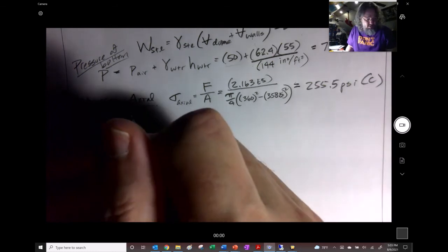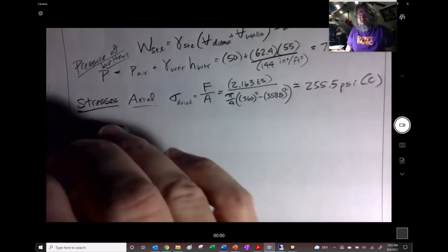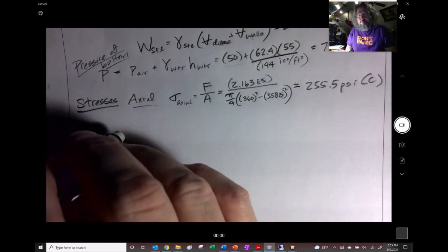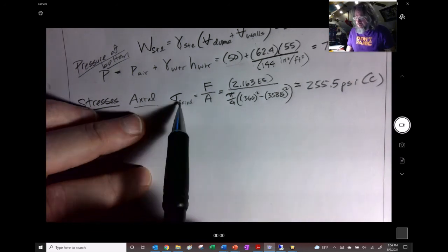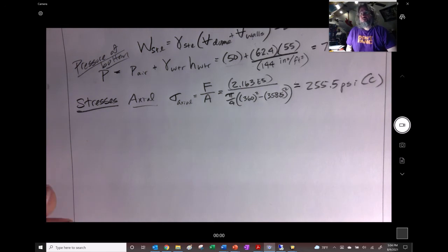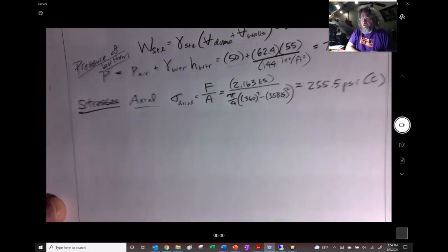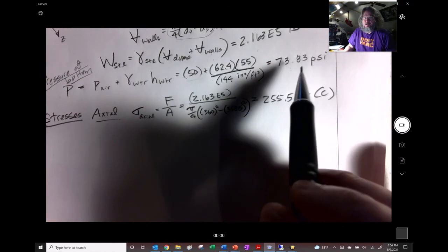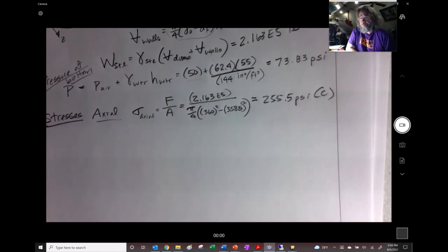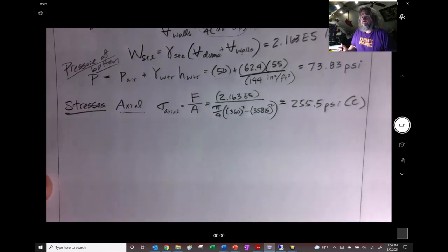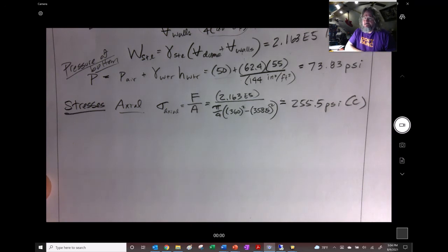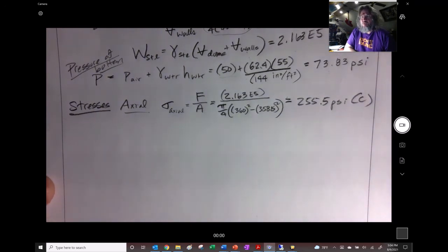Now, most of the other stresses are going to be due to the pressure vessel nature of this thing, right? This is an additional load that we have to consider. Now, the longitudinal is a tricky one. You might go and use this pressure right here to find the longitudinal, but you would be wrong. How do I know? Well, you see, you're just plugging and chugging. You're not actually thinking your way through if you were to do this. And full disclosure, the first time I did this problem, I totally overlooked it. Just was plugging and chugging. It is a trap. Don't fall into the trap.